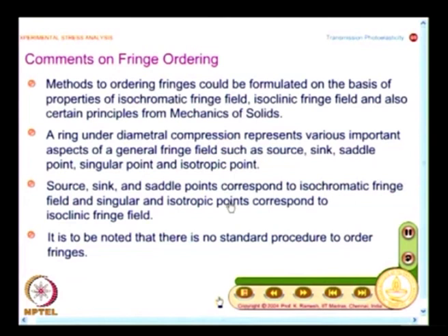If you look at photoelasticity, the arithmetic involved is very simple. For you to find out the stresses, the arithmetic is simple, but you need f sigma and you need the fringe order. And now, we take up how to label the fringes. One of the important aspects in any of the optical techniques is to find out how to label the fringe orders.